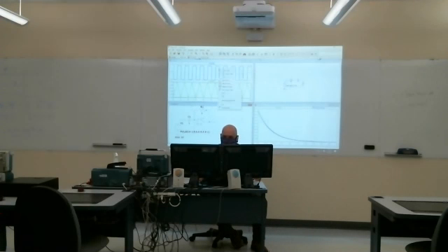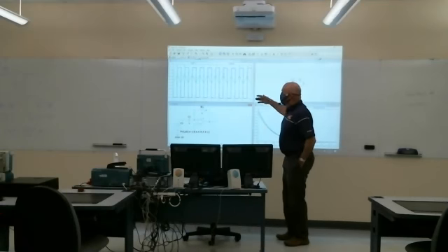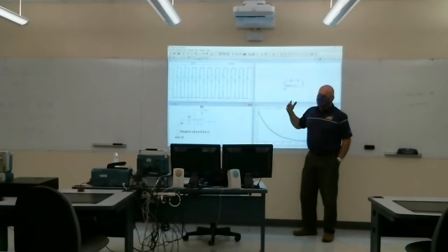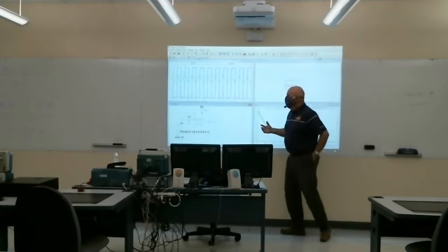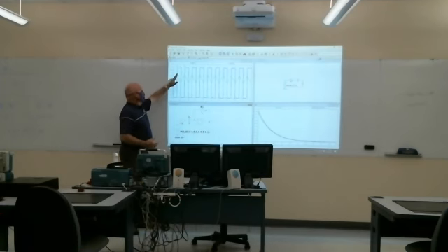So we put them both on the same plot. The scale's different. But remember it's inverting. Now the blue should be the derivative of the green, so the negative derivative. You notice here that the slope is positive, has constant derivative. So the derivative there is negative because it's an inverting op amp. Here where the slope is negative, the output's positive. Slope's positive, the output's negative.